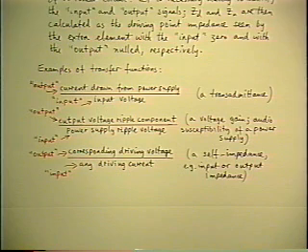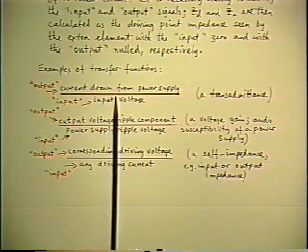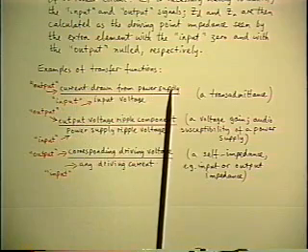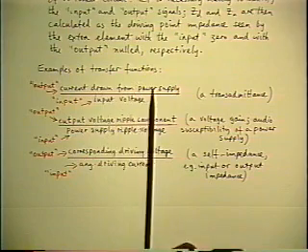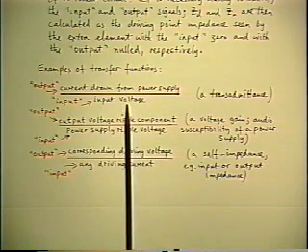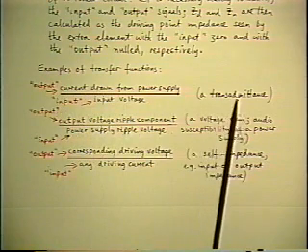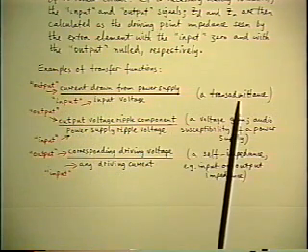That requires a subsidiary specification, because when you come to design the power supply, or maybe someone else is designing it, you have to provide an interface specification that says your amplifier is going to draw so much AC current out of the power supply, and which therefore has to be capable of delivering it. So another transfer function which is of interest for your audio amplifier is how much current is drawn from the power supply as a function of the signal input voltage. Now this is a dependent current over an independent voltage, and so this is a transfer function which has the nature of a transadmittance, current over voltage.